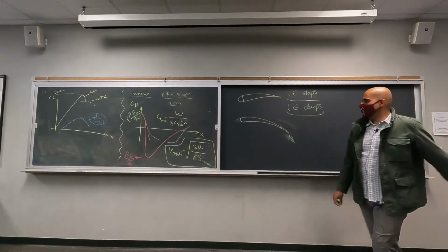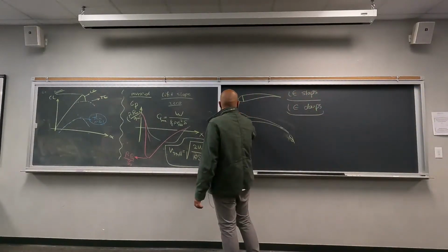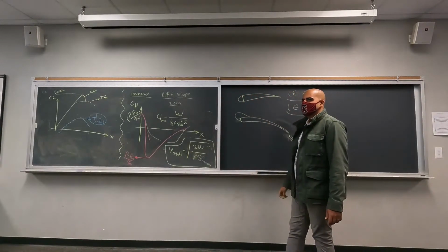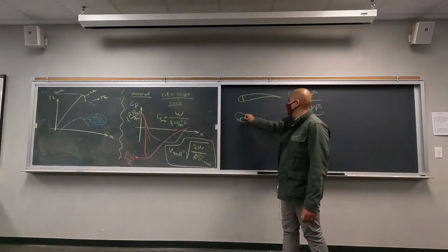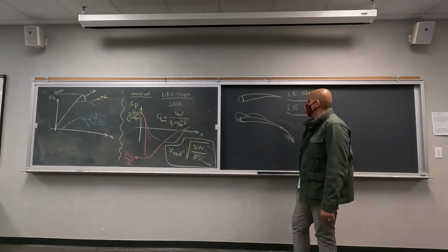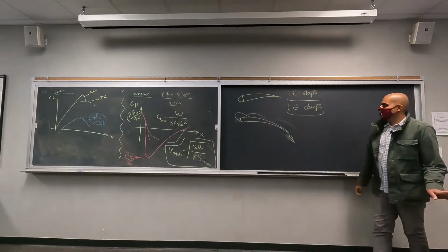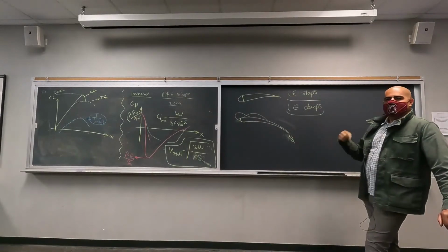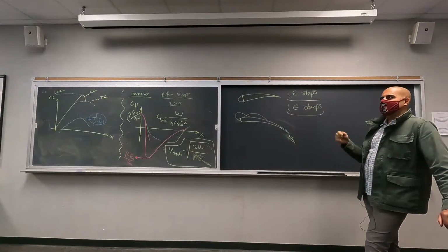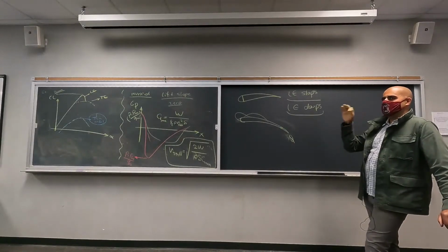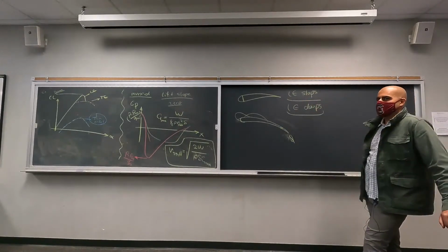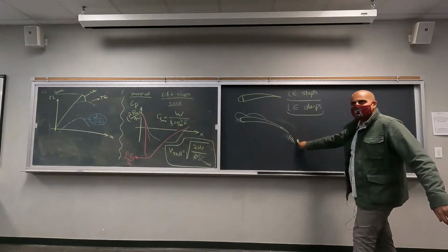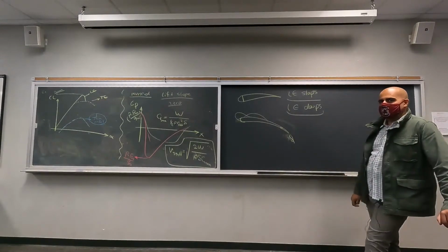An inflated, so you want to have this type of leading edge? So you want to increase the thickness? Is that it? That's an interesting perspective too. But increasing the thickness is going to make the flow separation just gradual, moving from a sudden separation to a gradual separation, right? The retractable thing, something like this, is something we will discuss, okay?